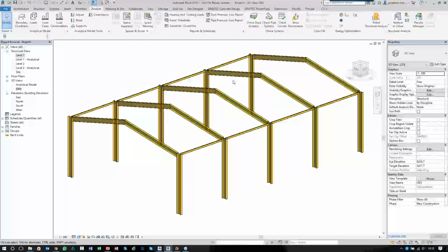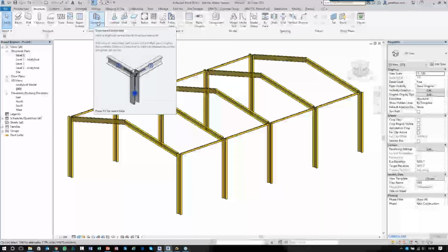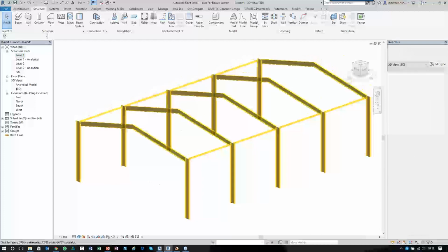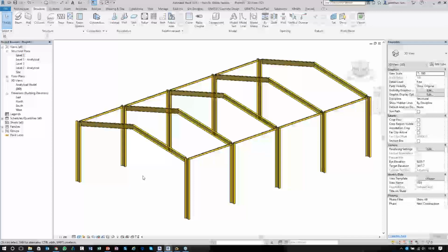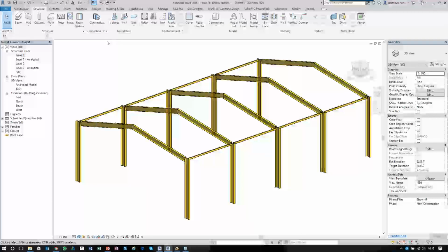Now to take this a little bit into the Revit platform, what seems to be happening more and more with our customers in the UK is that they're starting to look at the structure tab and the connection tab. In Revit 2017, the ability to add a structural connection was introduced. For those familiar with Advanced Steel, they are typically the Advanced Steel connections that have been ported across between the softwares. There's lots of things you can do in your template prior to starting. The big thing is to have the connections preloaded, because then they're sitting within the project browser.